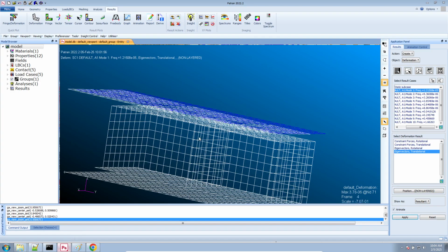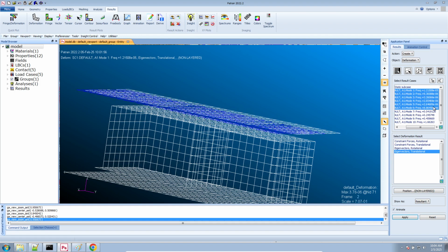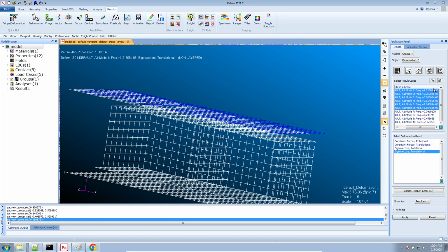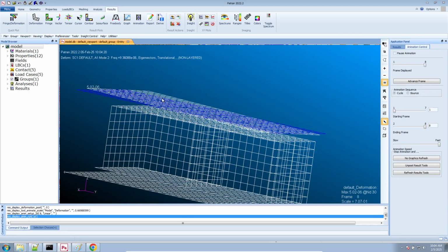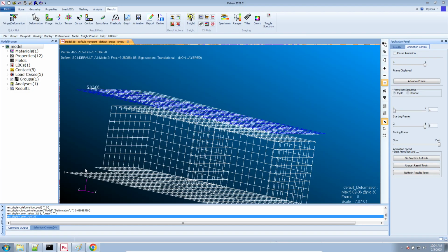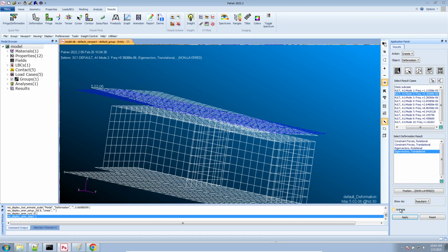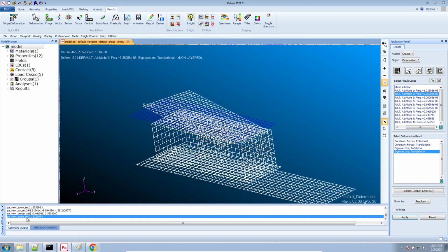That's why I always like using normal modes analysis. Here, if you look at the first 6 natural frequencies or mode shapes, they all have a 0 hertz natural frequency. That's because this mesh is not constrained in any of the directions. There's no constraint along the x, the y, and the z. There's no constraint that prevents rotation. So normal modes is very simple to confirm whether or not the mesh is properly constrained. Okay, so I think that sums up the end of the video.